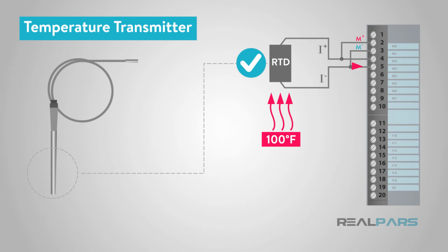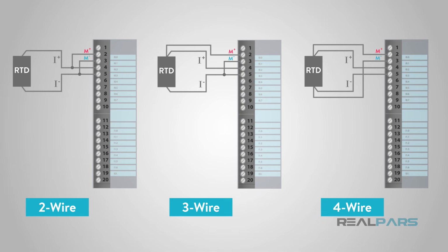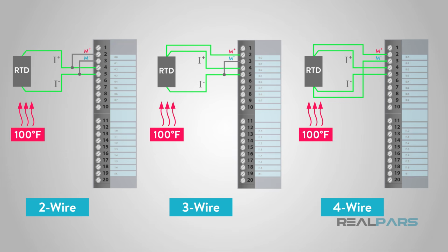This wiring diagram shows the simplest application of an RTD, called two-wire configuration. More accurate reading calls for three-wire or four-wire configurations. In reality, the distance between the temperature sensing point and measuring system calls for wiring, and since the real wiring has its own resistance, some measurement error sneaks in hereby. Three-wire and four-wire solutions are developed to remove this error.